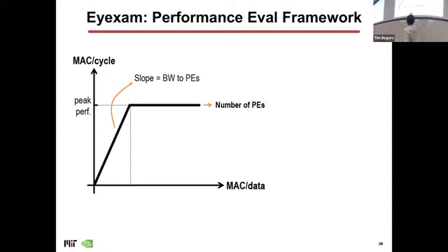Where the workload itself has enough compute per data, in theory, the machine is now limiting your performance, not anything else, because the workload itself actually has enough MACs per data. It's been optimized enough, there's enough MACs per memory read that in theory you could get all the way up there. If the workload is below this dotted line on the x-axis, what do you think that means? Not you, you already know what this means. So the dotted line is magic, because it says the workload theoretically has enough compute per data to satisfy the machine. What happens if I'm to the left of that dotted line?